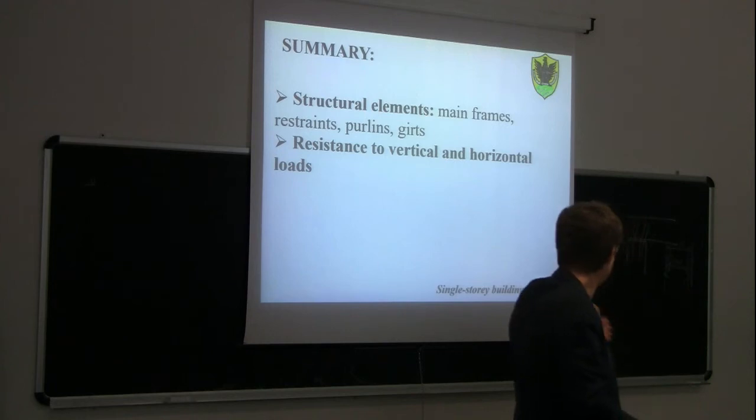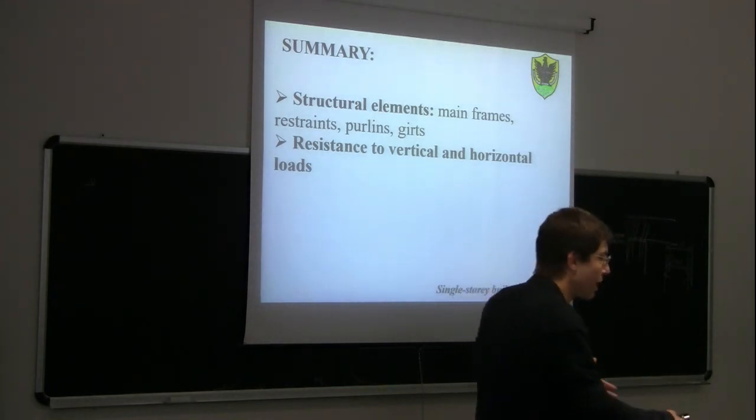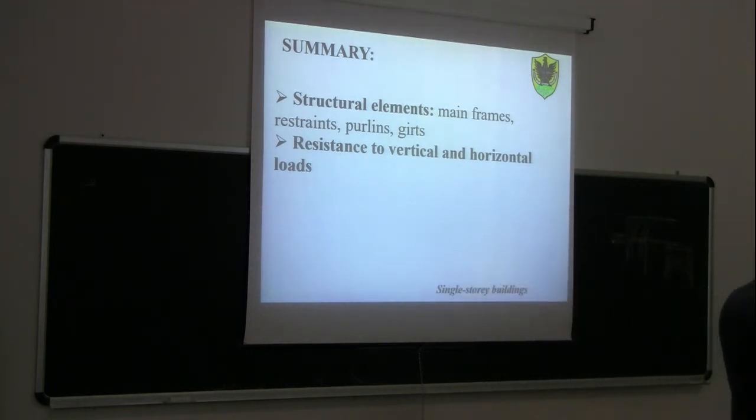Of course, now we will talk about timber members and joints, but in terms of organizing the building to make it able to resist horizontal and vertical loads, I would say that this kind of structural system is almost material independent. Of course, if you do it out of cast in situ concrete, it will be completely different. But nobody will do a building like this out of cast in situ concrete. So it's always a kind of prefabricated building. So many of these concepts can be easily extended also to other materials.